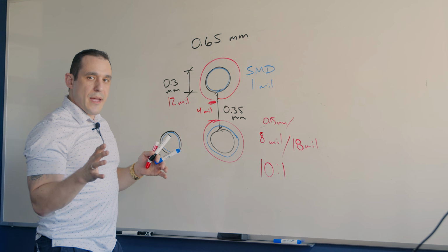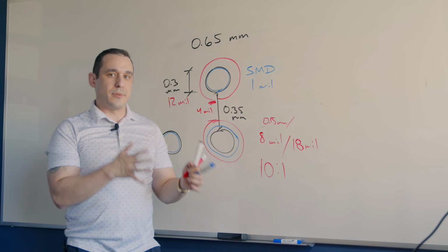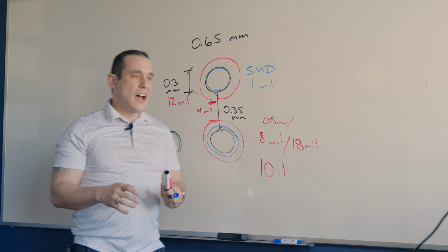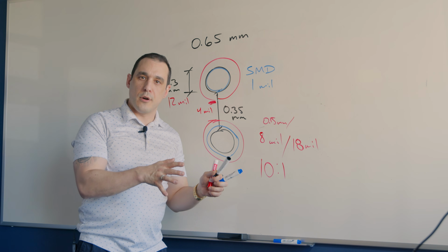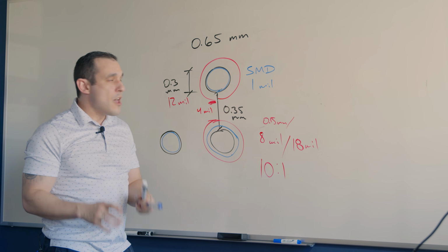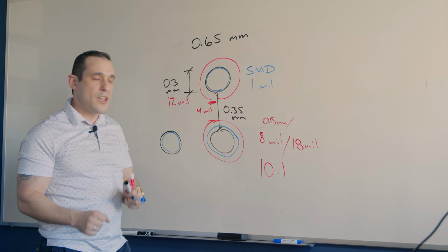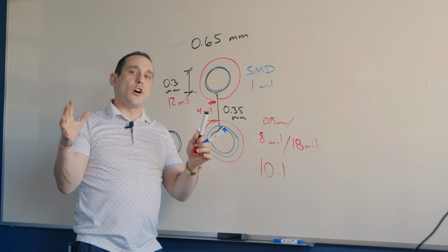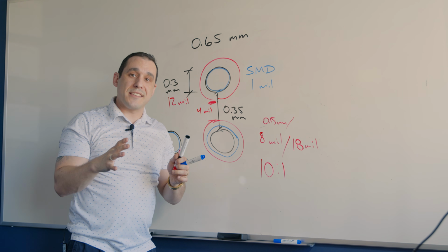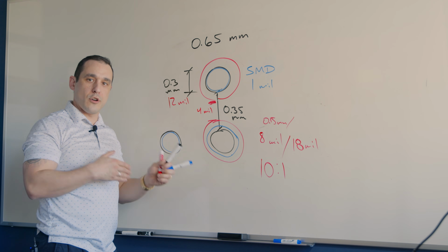Now I've talked about solder mask expansion many times. I've shown examples of bad solder mask expansion applied automatically in design reviews, and I've talked about it a little bit on finer pitch components like QFNs and QFPs, and even some examples with BGAs. But once you get to these finer pitch BGAs like a 0.65 millimeter BGA, you definitely want to apply a larger pad and then a negative mask expansion, have an SMD pad to ensure consistent soldering everywhere across that BGA footprint.